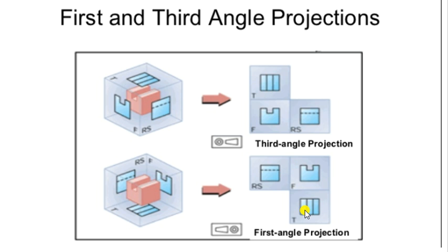How these diagrams came, I will explain you. Just look at the first angle projection method and the figure. You can see that there is a notation F, the letter F showing the front view. That means observer is standing and looking towards the object exactly from the opposite side of the frontal plane, so that front view will be on the frontal plane.